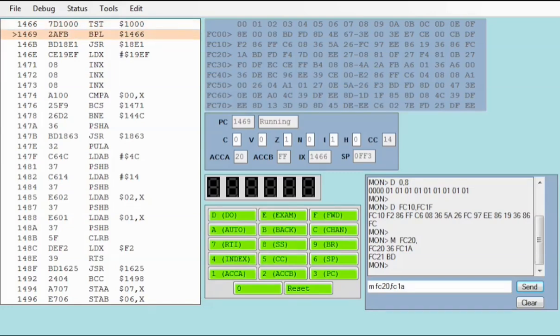So what's remaining is the second extra ROM, which is a BASIC interpreter, Tiny BASIC, and unfortunately that just doesn't want to work. I'll get a peep out of it, but that's about it. The way to do that is we use the go command. We're still in the Phantom monitor, and we go to 1C00.